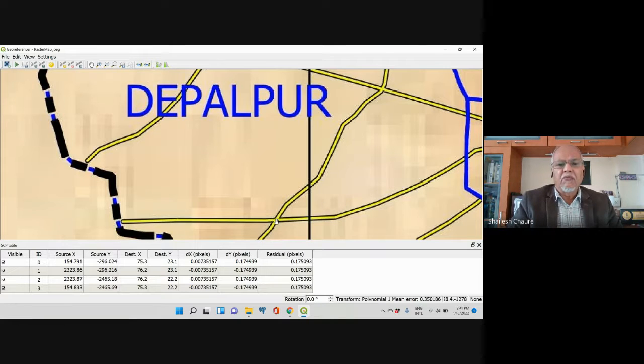Suppose you have a colony map. You are developing a colony and the colony map is there, and you want to georeference it. What will you do? You'll go to the corners of that colony boundary, or use some major roads in the colony, but it's better to pick up the corner values. Whatever polygon defines your colony, you move to each corner, so that the corner should be visible on the ground as well as clearly identifiable on the map.